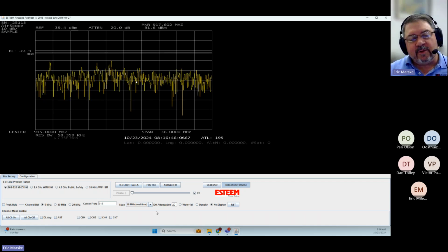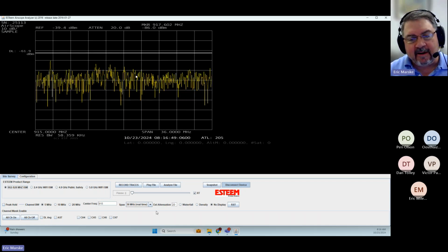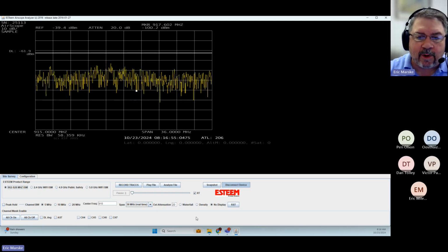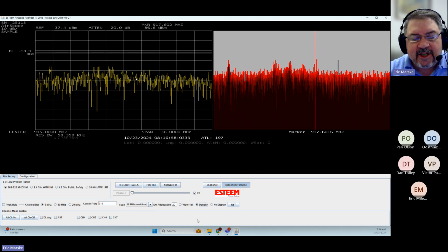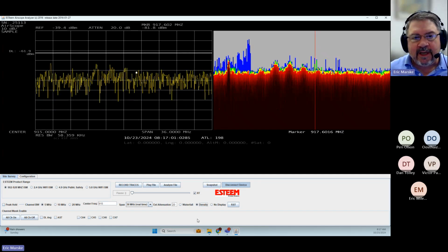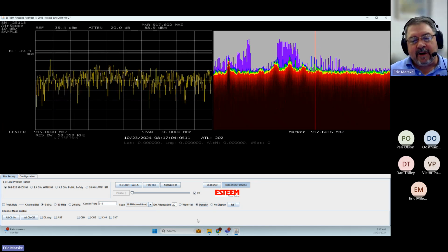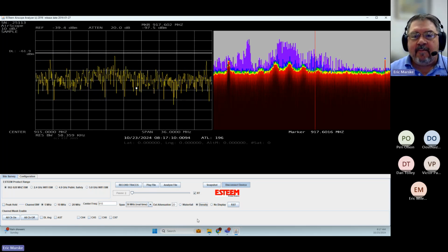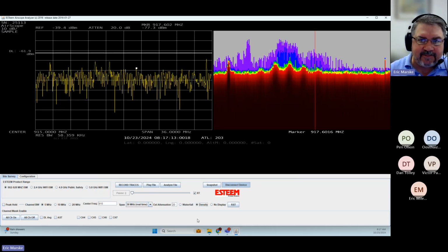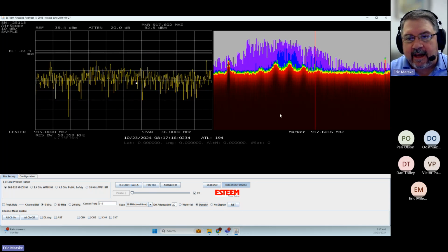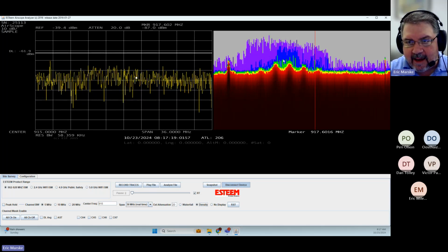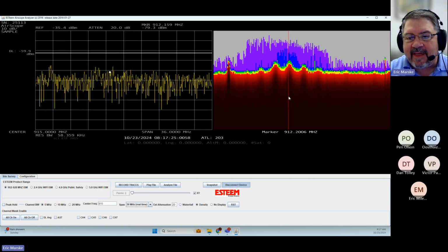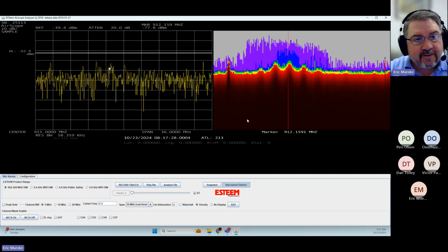So what we've done is we've actually put two spectrograph displays within here. The first one, which is very similar to the way peak hold works, is what's called density. Now, if I turn the density map on, this starts looking at that frequency channel and will continuously keep adding information in there based upon the transmitters that it sees. Okay, and as you can see here, we're building kind of a profile in this band over here on the right hand side. I can move my marker over, and it's running about that 912 megahertz frequency band.